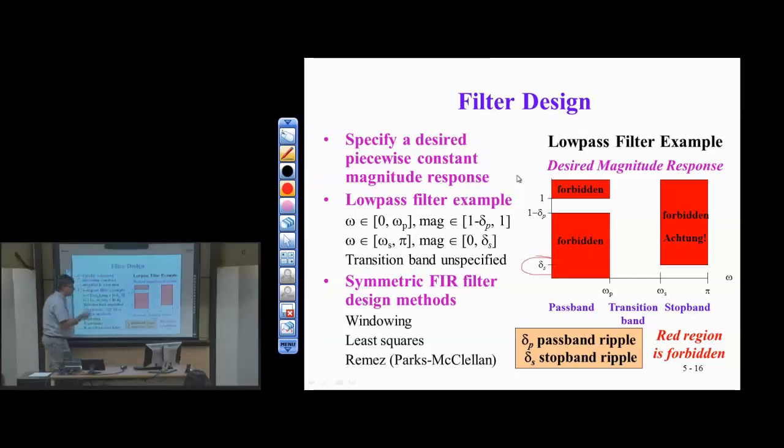For FIR filtering, we actually allow the variability to go plus or minus 1 in linear units. Now, a more common set of units for filter design is not linear units, but dB. Okay, so if a linear unit is 1, what's the dB for a linear unit of 1? 0. So in dB, this is 0. So 0 dB should be in the center of the passband of your filter that you design.